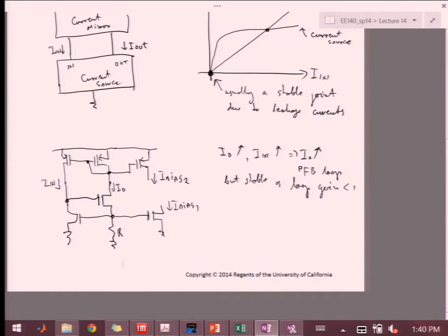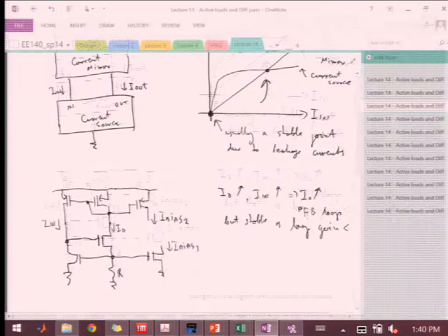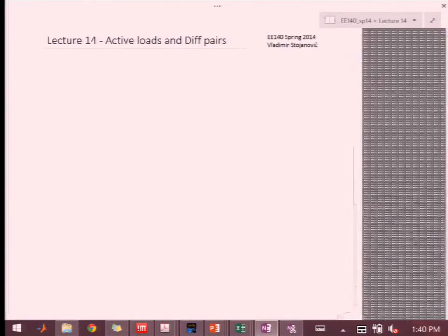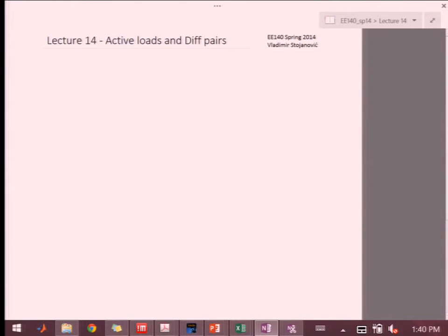would have to have a startup circuit. So if you were to build this for real, you would have to have a circuit that will make sure that you end up in this point as you put your supply on. And so I'll give you an example of a startup circuit. So if we go and redraw this thing just real quick.